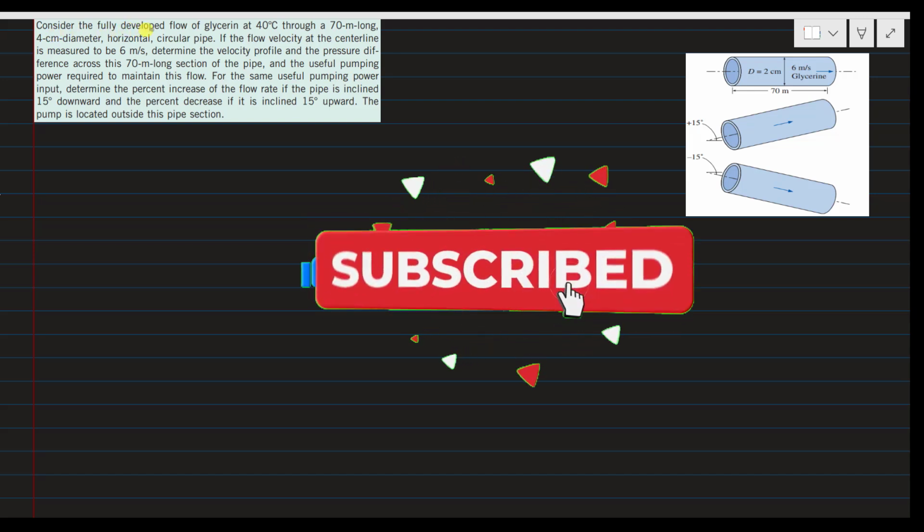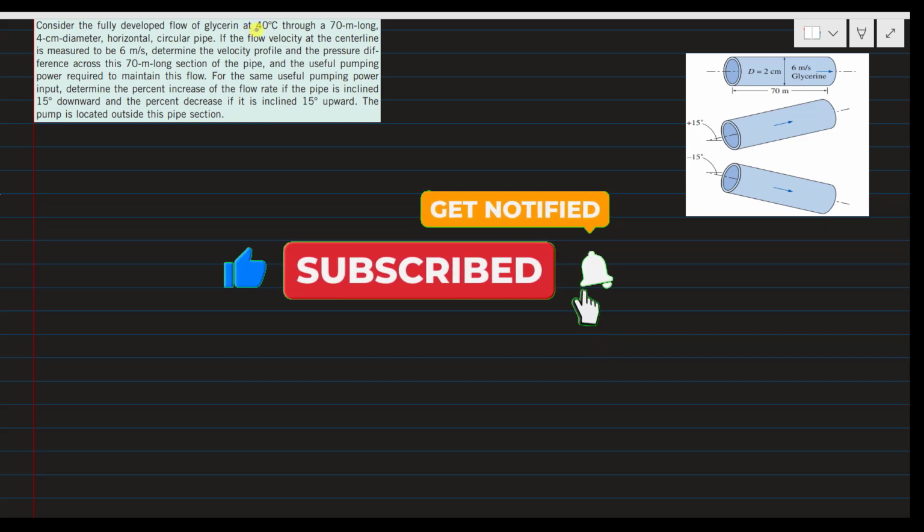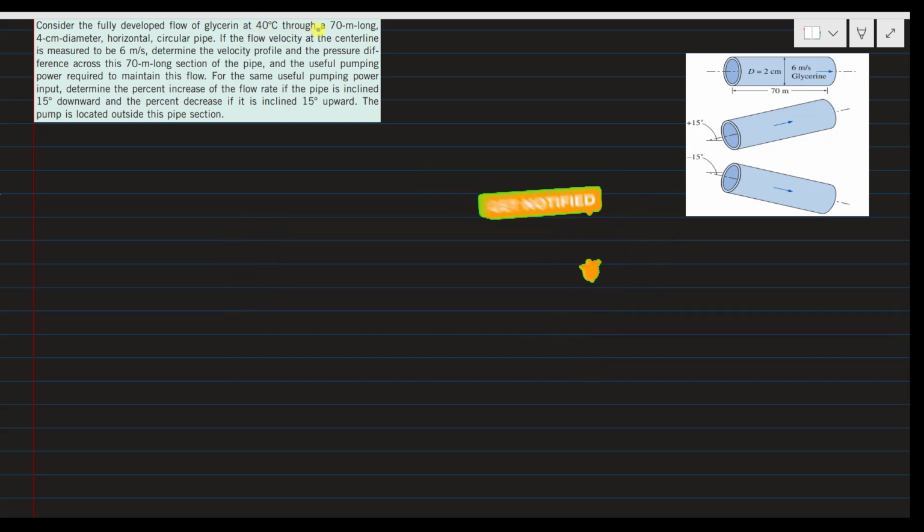Consider the fully developed flow of glycerin at 40 centigrade through a 70 meter long and 4 centimeter diameter horizontal circular pipe. Here it is shown. The flow velocity at the center line is measured to be 6 meters per second. Determine the velocity profile and the pressure difference across this 70-meter long section of the pipe, and the useful pumping power required to maintain this flow.